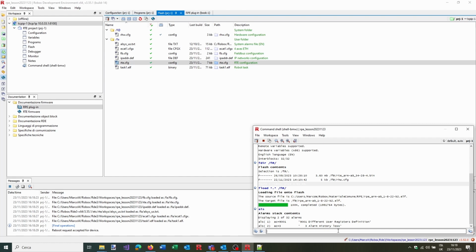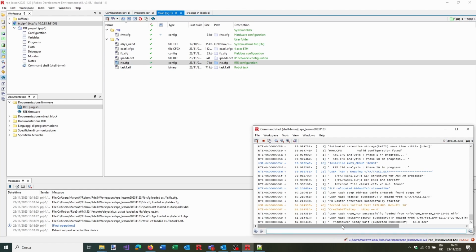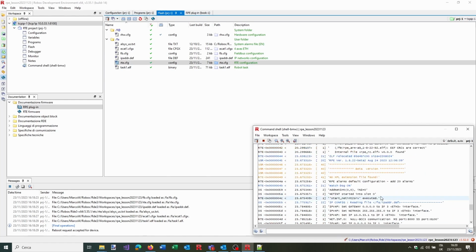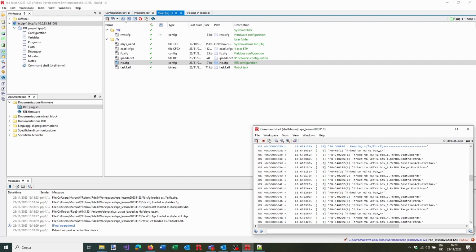Now I press twice the button below the screen, which is the Advanced button. The Advanced button will reset the alarms and then will allow the system to try again to start. Now the system is moving so slow. Let's ask the report why this is happening, and let's debug the mistake we made. Now we have the report, and inside the report we can read many things.